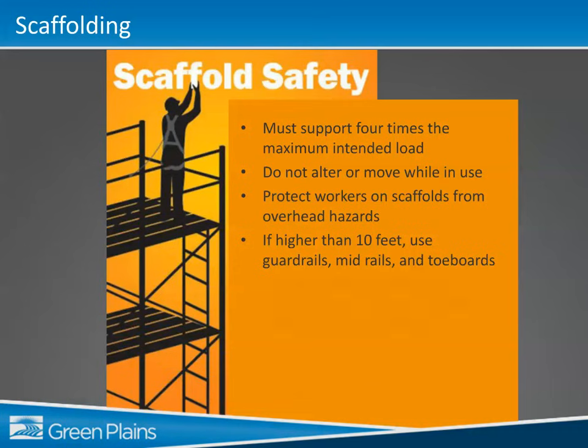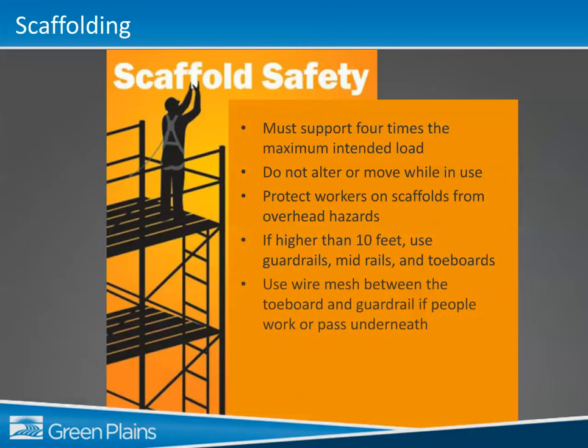If people are working or walking underneath the scaffold, wire mesh or similar material must be used to prevent tools or material falling to the next level, and all scaffolding must be equipped with a ladder or equivalent to provide safe access.